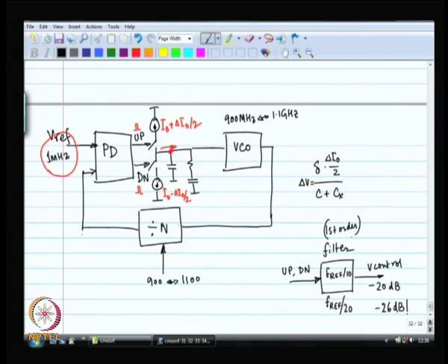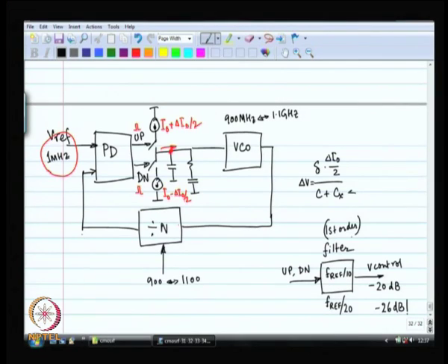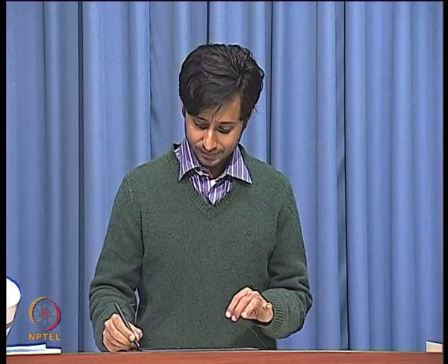Right. So, what I am suggesting over here, is that consistent? If I half the bandwidth, that means I am doubling the capacitance. If I double the capacitance, then the size of these delta V's becomes half. So, it is the same phenomenon. So, it agrees. So, make the loop bandwidth smaller, you are going to get even better performance. You can get rid of these spurs completely.